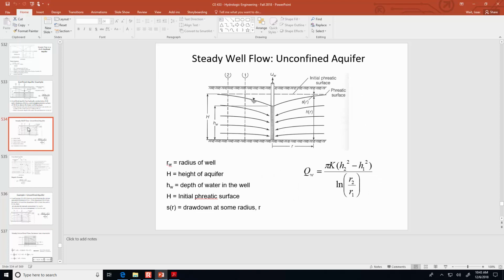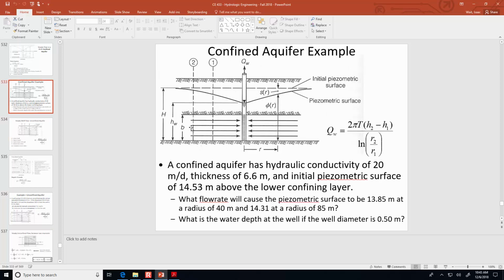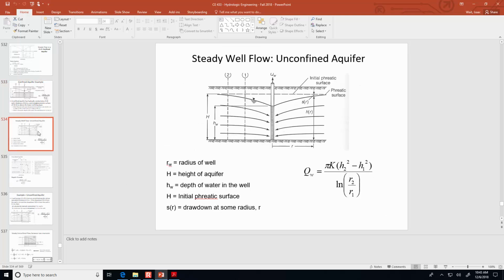And if it's only a horizontal movement, there's going to be more energy available because, if you think about the flow path, you only have a lateral flow path towards that well. But down in this situation, you've got a longer distance, and so there's less energy available. And so squaring each of the individual water heights, I think, accounts for that effect.